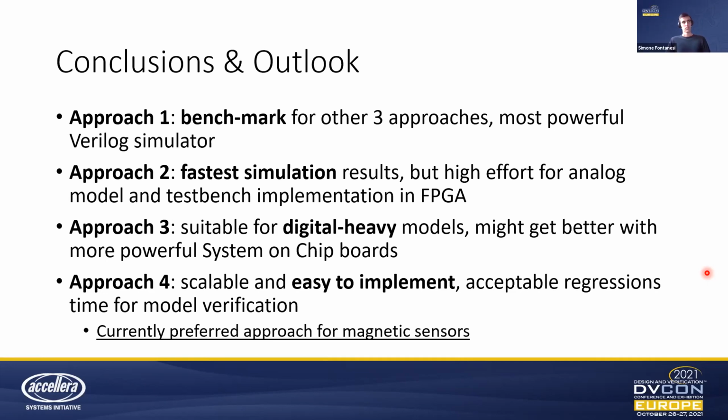So, Paul, maybe please correct me, but I would say that approach 4 can be suitable for any kind of system. Yes, because this is purely virtual. So COSEDA provides you a coupling interface: if you have a module which only has a SystemC interface, you can right click on the model and generate the wrapper, and this is included in your schematic, and you can place your RF system around it. So if you have any digital stuff you want to offload to an XSI simulator, then yes.